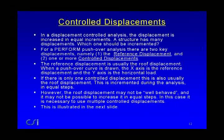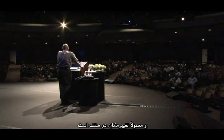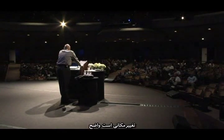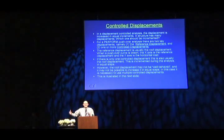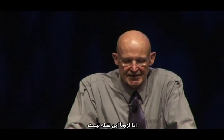And so that is the reference displacement. But there's a second type of displacement, and this is the one that you want to increment equally in each step. Now, the obvious choice, and the choice you frequently use, is the same displacement, the roof displacement. But it doesn't have to be.